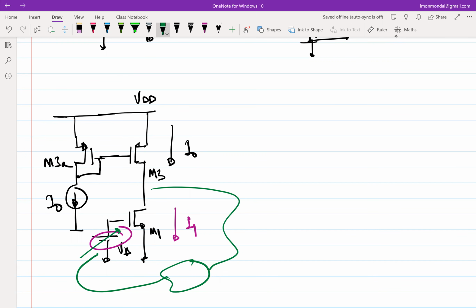The other way to think about it is that what we are trying to achieve is an amplifier whose amplification factor should be high when we analyze it in open loop. Well, that statement is not exactly accurate. What I'm trying to get at here is that if you break the loop, you should see a lot of gain. That's why we analyze the amplifier in open loop. But the assumption in the back of the mind is that I'll put it in a closed loop, because an amplifier cannot work in open loop. It will saturate, because of difference in current, it will either go to VDD or ground. So you never use an op-amp in open loop, for example.